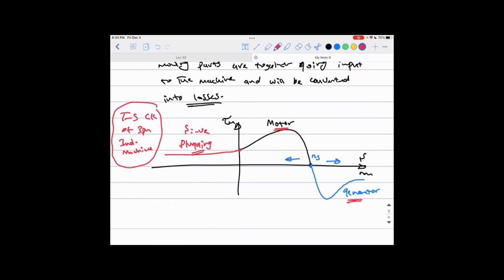In the same way, we studied the lab experiments used for determination of the equivalent circuit parameters, so we can use this equivalent circuit to predict the motor performance. After that, we talked about two very important topics, which is the speed control of the three-phase induction motor using different ways of speed control, with so much emphasis on the most popular one, which is the V/F speed control using power electronic converters.